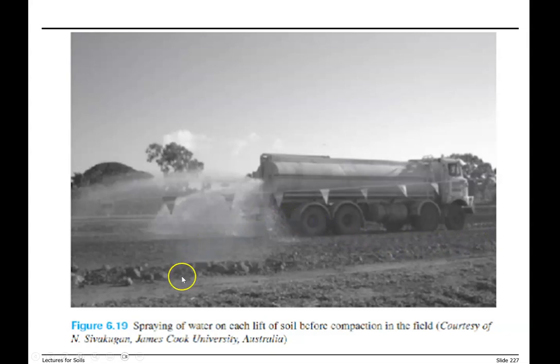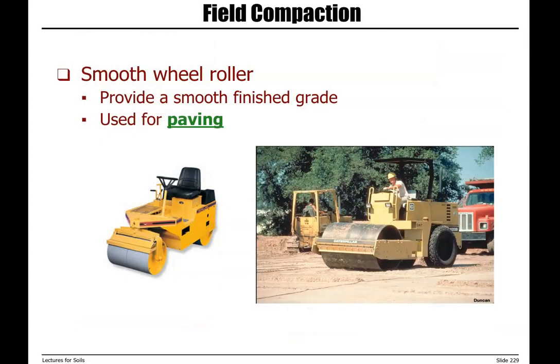This is an example of spraying water on each lift of soil before compaction in the field. Let's look at some equipment that are used for field compaction.